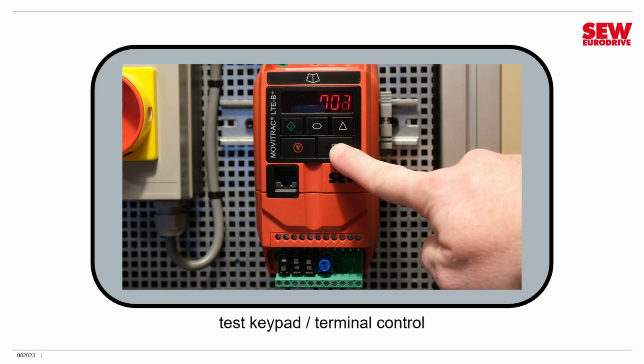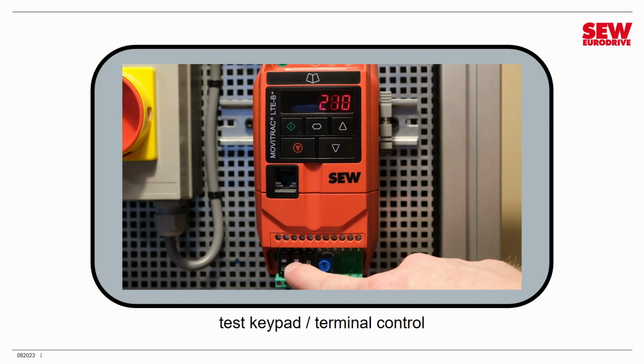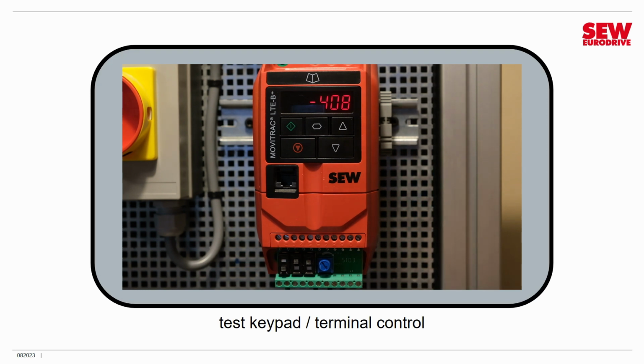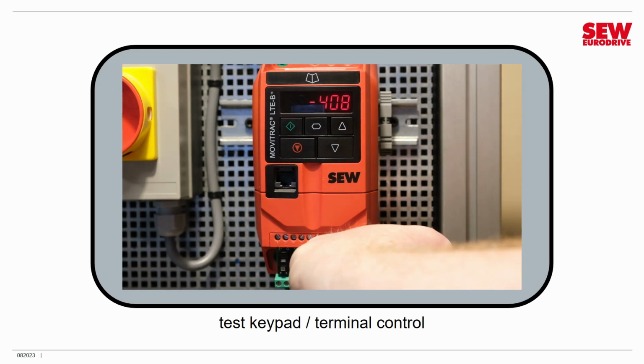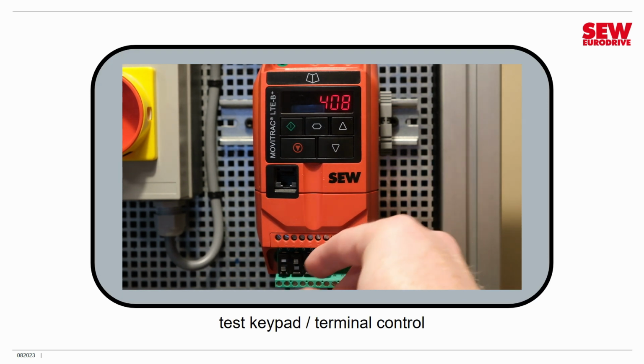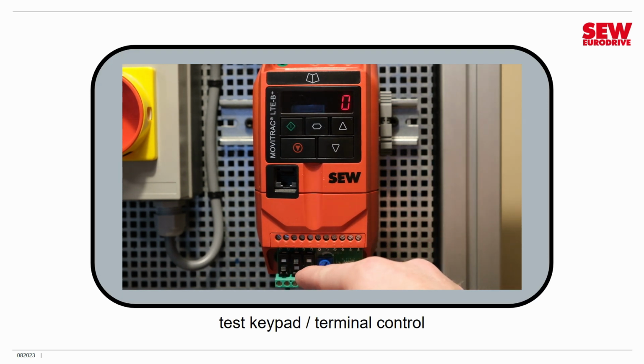But now I'm going to switch to using the push buttons. So I'm going to turn DI2 on, and as long as you hold the push button down, the drive will speed up till it hits maximum. I'll pulse this one to simulate pressing the button for a brief time, and you can see that slows down in little bursts. I'll go down a ways. And now I'm going to use the potentiometer, which is behaving like a switch here, to reverse direction. If I turn it all the way up, it reverses. If I turn it all the way down, it goes forward. So it's acting digitally here. Let me slow the drive down to a stop.